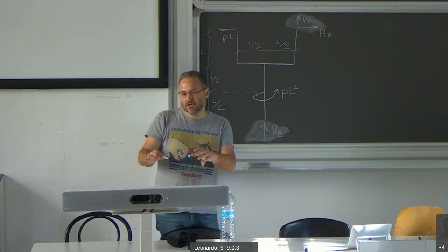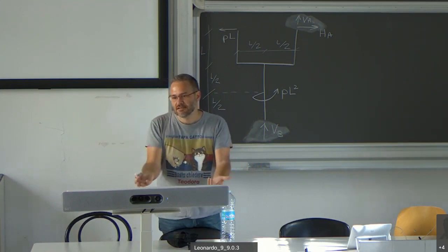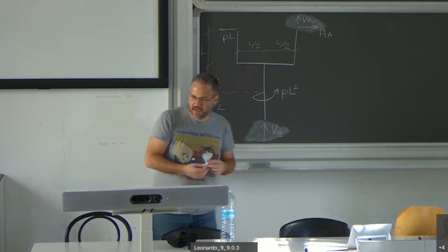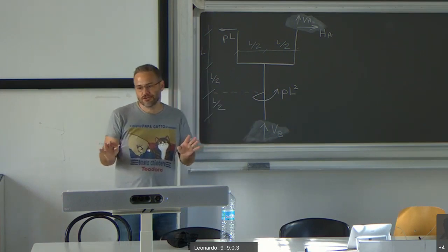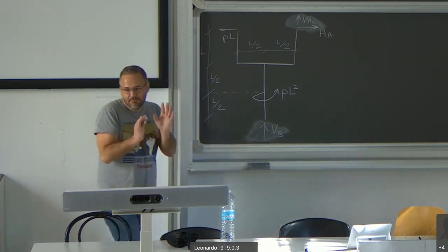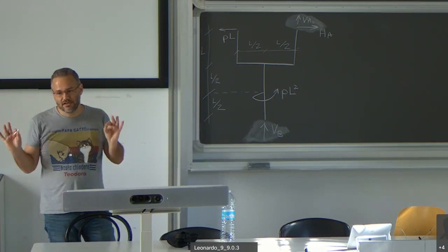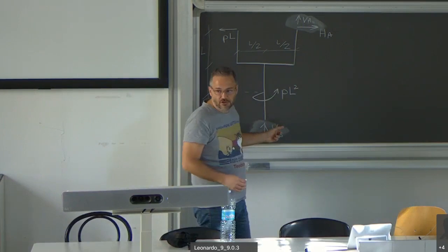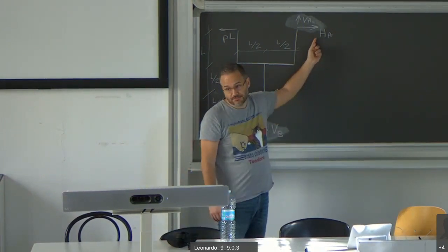Now, of course, I assume you're not satisfied with just this answer, so we're going to solve the structure to prove what I mean, okay? First by equations, and then by looking at the structure, okay? Clearly, simply looking at the structure, without doing any calculation, we have 1 and 2 vertical reactions, and we only have 1 horizontal reaction.